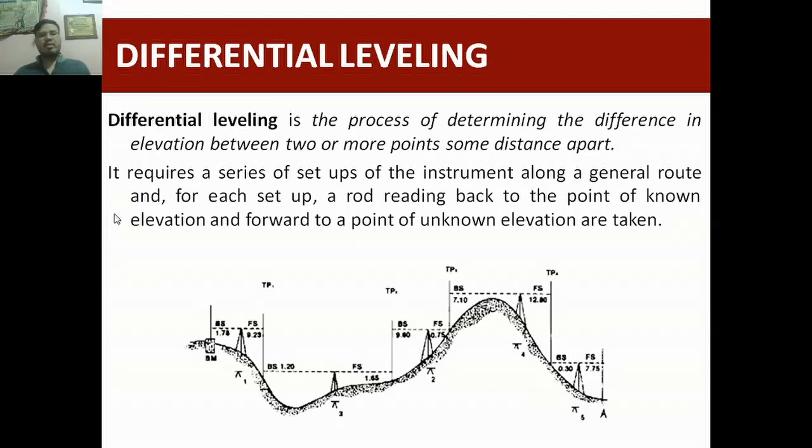It requires a series of setups of the instrument along a general route, and for each setup a rod reading back to the point of known elevation, which is this one, and forward to a point of unknown elevation are taken. So that is differential leveling.